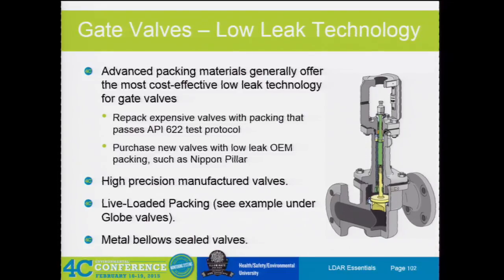The live load packing is another one where they can do this again online. So you're also getting much greater seals now after you do a drill and tap and loading it while it's still in process. You don't have to take the whole thing apart and repack the valve anymore. So all this stuff is bringing down leak rates and keeping these things from leaking as chronic leakers.